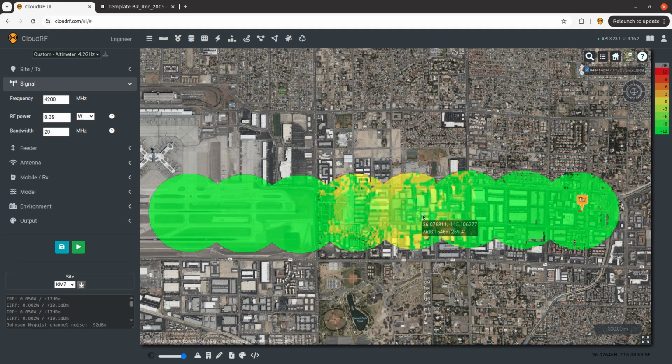This is an extreme example we've modeled here. We've used the maximum power parameters. This is as bad as it could get. Also, the siting here at the end of the runway is a terrible site for a high-powered C-band cell. But the risk is still there. It's very low, but you can help the pilot in an ILS landing by following instructions and keeping RF noise to a minimum.